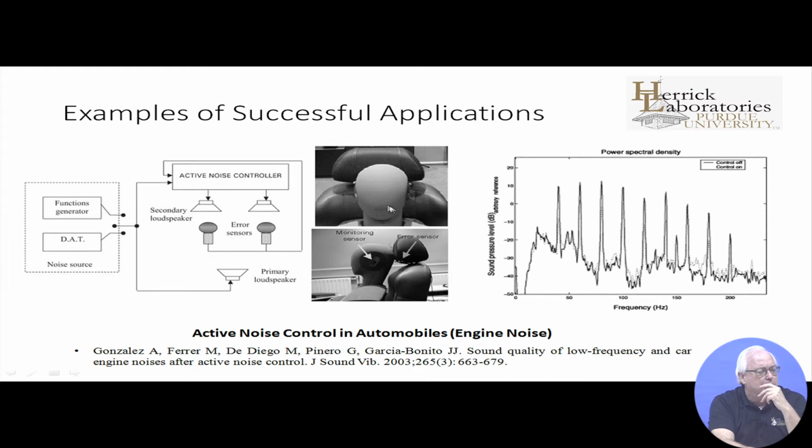Something else which a fair number of people are pursuing at the moment is again a local control strategy, where in an automotive application, instead of trying to reduce the noise throughout the entire vehicle interior, you just try to control the sound level in the vicinity of the driver's head, which is convenient because there's an opportunity to put secondary loudspeakers in the headrest, for example.